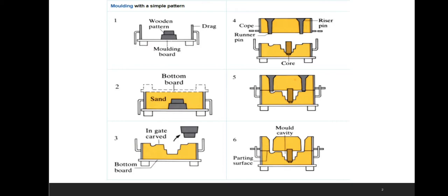In addition to the sand, a suitable bonding agent, usually clay, is mixed or occurs with the sand. The mixture is then moistened, typically with water but sometimes with other substances, to develop the strength and plasticity of the clay and to make the aggregate suitable for molding.